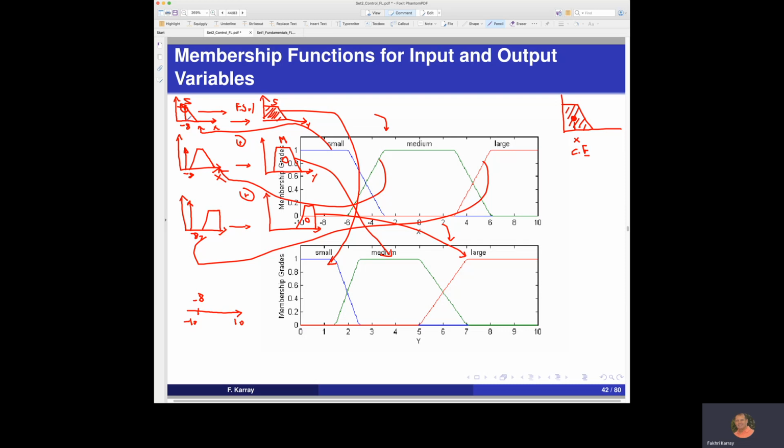So this is an example of how to utilize fuzzification, using a singleton fuzzifier, then the aggregation, and then the defuzzification. Okay, so this is the aggregation. We have combined all of them, but only the first one gives some representation of the membership function. So this is the aggregate membership function, and this is the center of area, which gives us the center of gravity for this particular value, and that's the value for the decision-making process. This is what we want to say in this type of representation for this system.